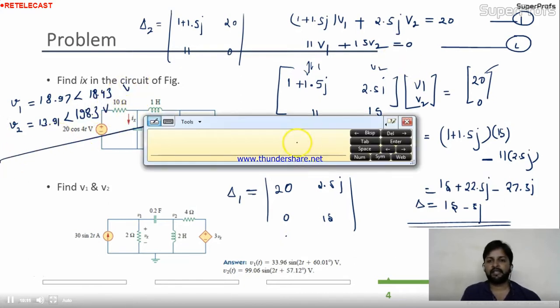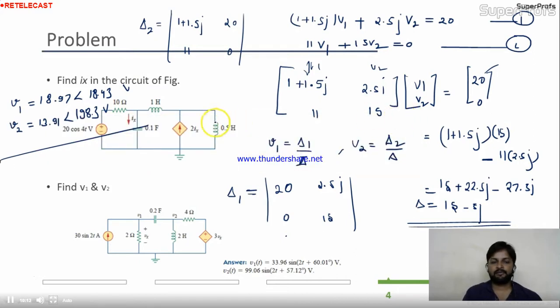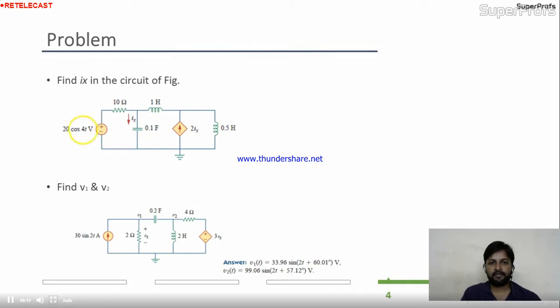So like that you have to solve. So friends, if you observe, this is the AC circuit, okay, fine. But when you put the frequency's value, you can convert this entire circuit in the form of impedance function, and once you convert it into impedance function, you are free to apply KCL and KVL or any circuit theorem in the circuit.